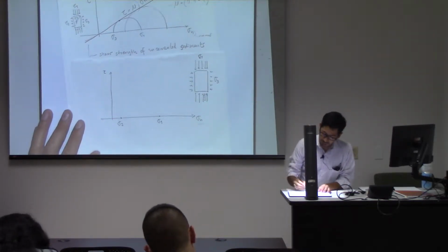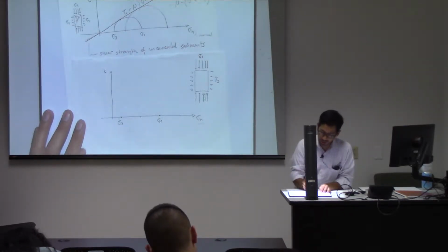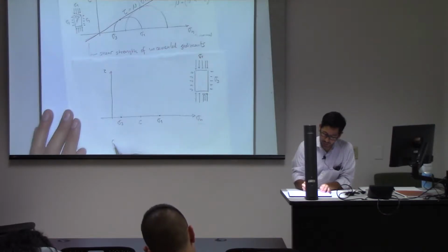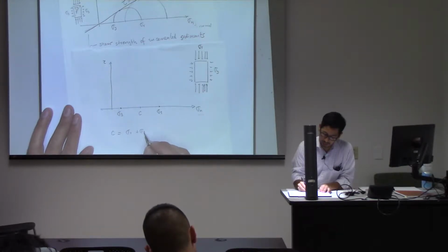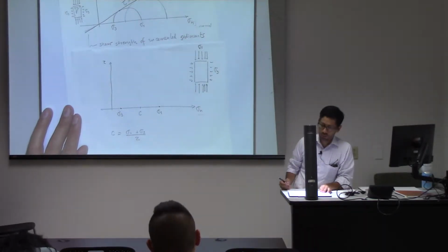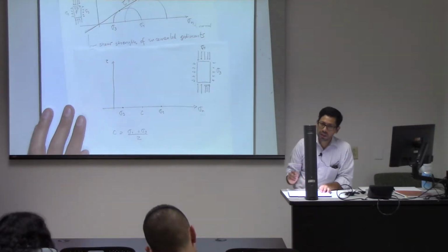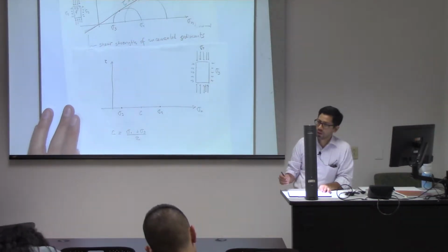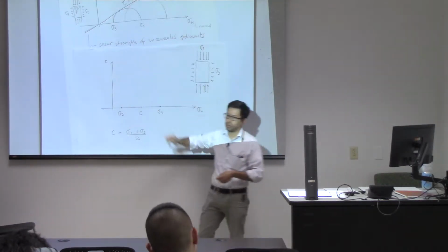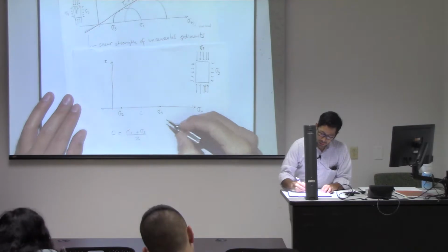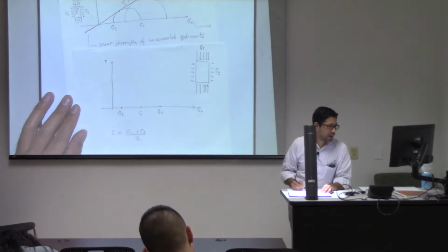I like to draw Mohr circles by always finding here what is the center. In 2 dimensions, the center of the Mohr circle is going to be sigma 1 plus sigma 3 divided by 2. And since this is the center of the Mohr circle, this is going to be a perfect circle. And just for convenience, because it just looks the same, I'm not going to draw the entire circle, but just half a circle. And if I'm drawing a half circle, the radius is going to have that height, more or less.